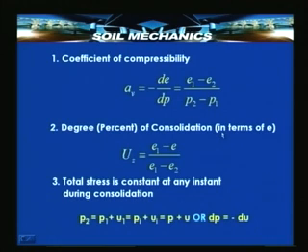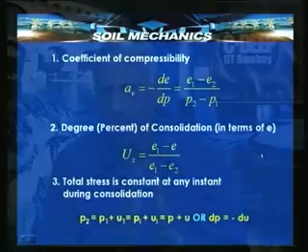Then we can also define a parameter called the degree of consolidation, because we have just seen that the compression at any intermediate time during the entire process of consolidation is proportional to the amount of volume change that has taken place until then.